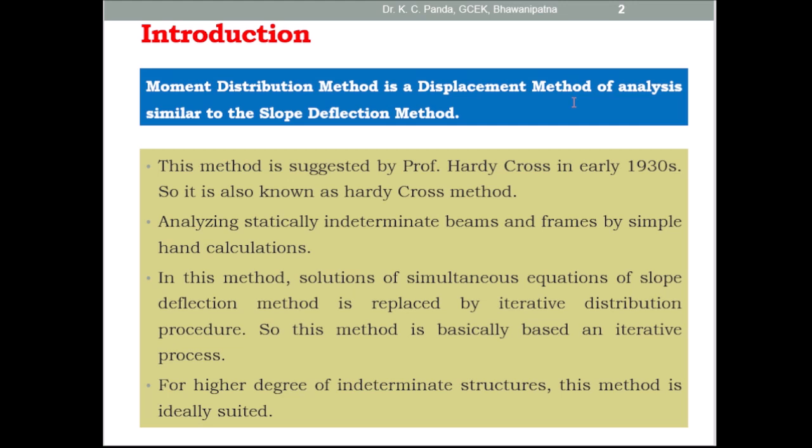The moment distribution method is a displacement method of analysis. Essentially, it is a method to solve the simultaneous equations in the slope deflection method by successive approximations by hand that may be carried out to any desired degree of accuracy. Basically, moment distribution method is an iteration procedure.